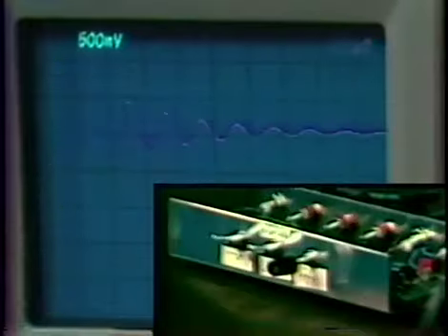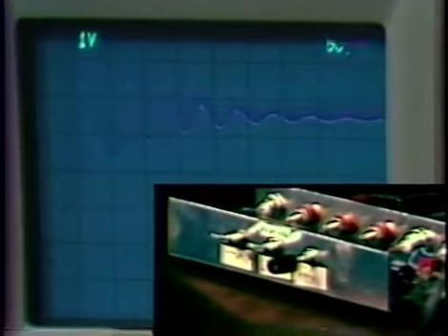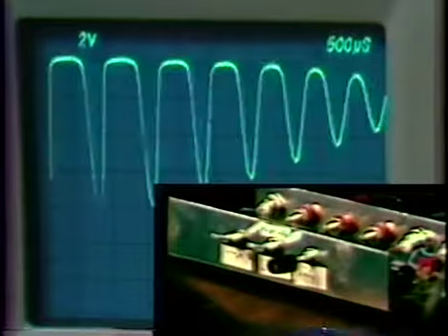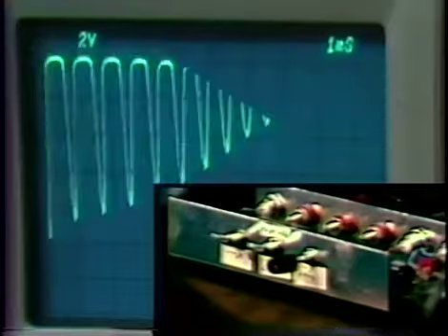Let's see what happens. We'll up the input amplitude. We're just driving the system harder now. Let me change the generator so I can get a little larger signal input. Now all of a sudden we're beginning to get into the nonlinearity. Notice the flattening at the top and so forth. Things are getting worse. All of a sudden the system pops into oscillation.